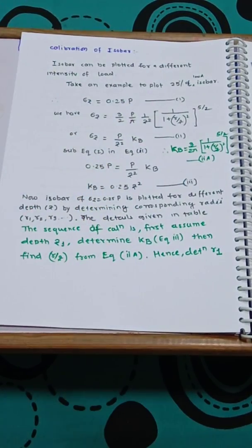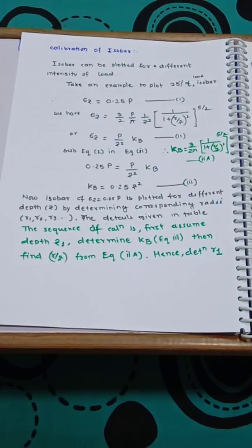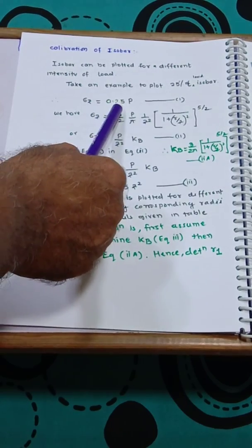Suppose I want a stress of only 10 kilonewton per meter square out of 100. I have to identify those vertical distances and radial distances, the points, and form a contour or a 3D diagram on which the stress is just 10 kilonewton per meter square. So in terms of intensity, I can consider it as a certain percentage of the load. For example, here 25% of the load.